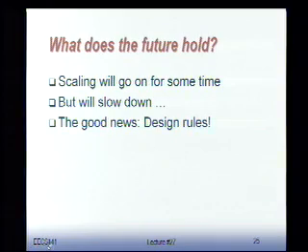You go to TSMC, you go to IBM, the run-of-the-mill process these days is 65 nanometers. Everybody moved to that. State-of-the-art designs are now being shipped in 45 nanometers. If you think of the latest parts from Intel, 45 nanometers is the technology of choice. So 45 nanometers is an absolute given.